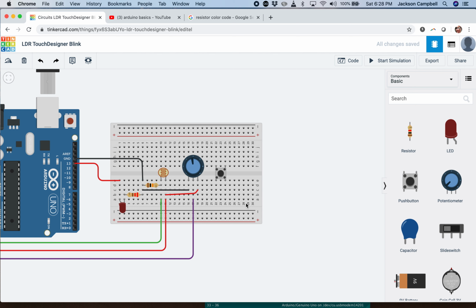That's probably the clearest way, but it requires us to use another pull-up resistor and extra jumper cables, and it's really just not necessary because there are built-in pull-up resistors in the digital pins. If you set them as INPUT_PULLUP, then it will engage a pull-up resistor, and it makes the button work the opposite way, where now it's reading it as an input, but it's sending 5 volts out of that digital pin, and it also sends it through its pull-up resistor to ground, so that does that for you, and you don't need to add it.